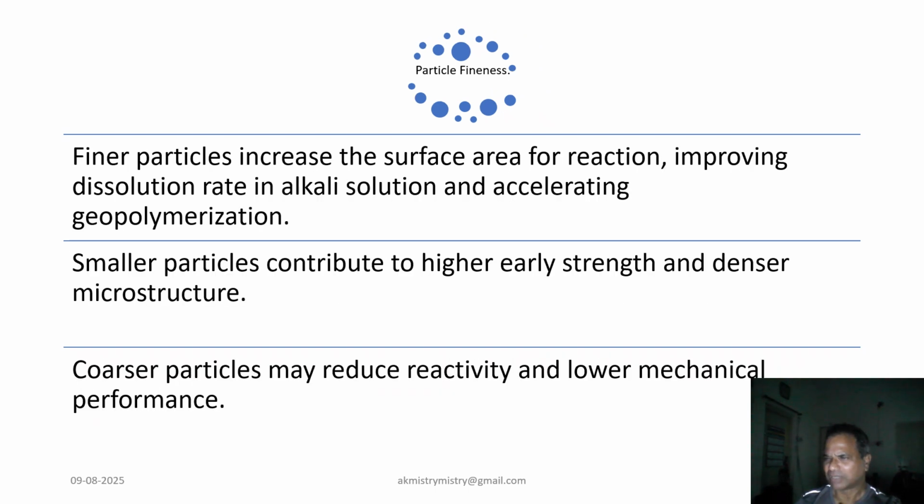Now coming to the size of particle, that is very important. We can say alternatively particle fineness. So smaller particles react faster and make stronger geopolymers. They help form a dense structure. Bigger particles don't react well and can weaken the final product.